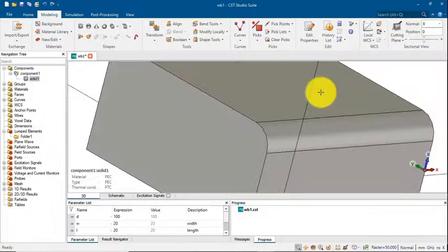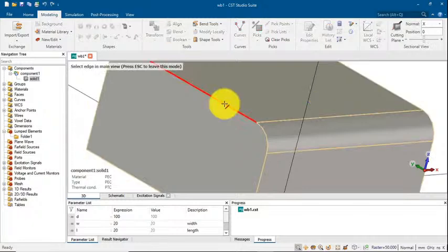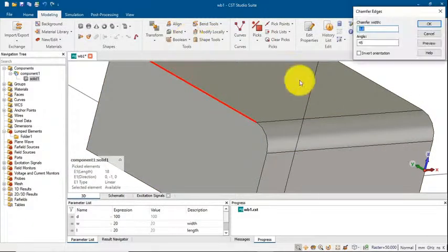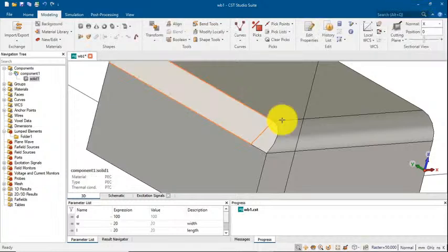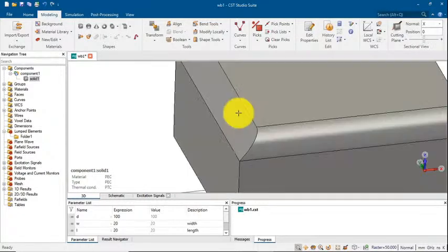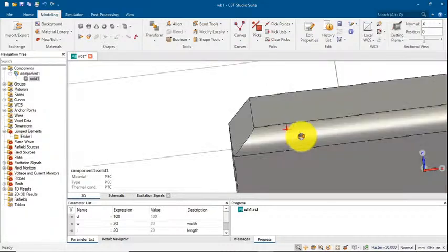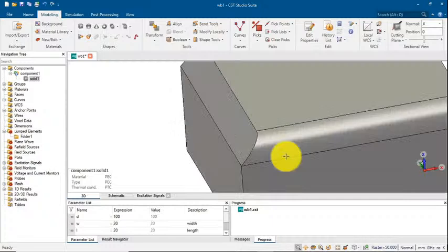This is the blend. Let me press E again and choose this. And now I will chamfer it with 2. Preview. Okay, you see the difference? This is the chamfer. You cut from it as a rectangle, as you see. And this is the bending way.